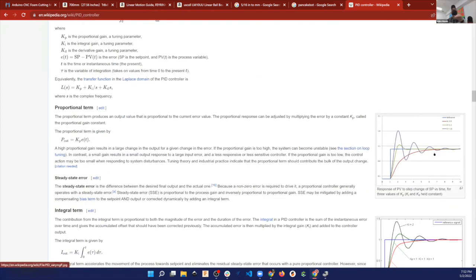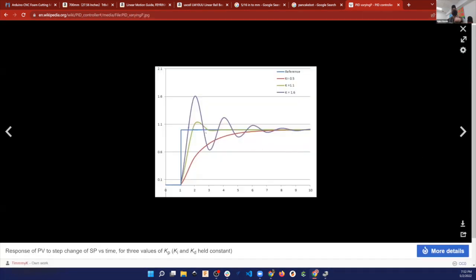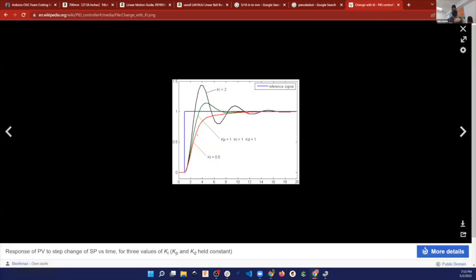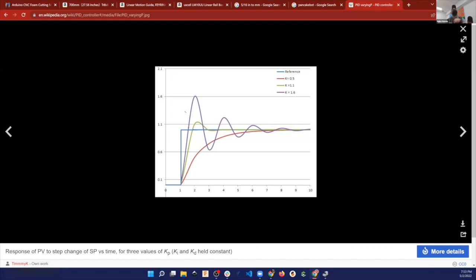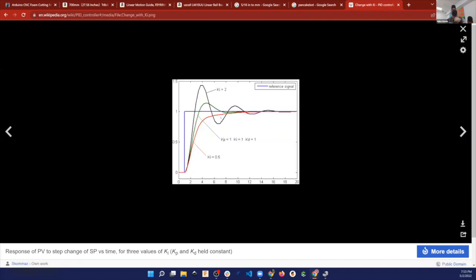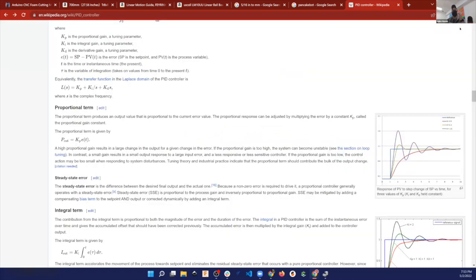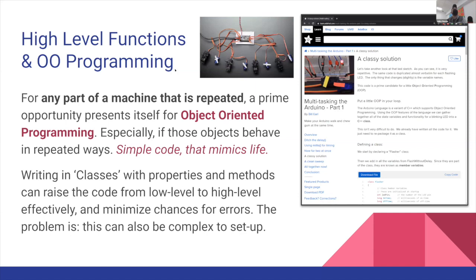It looks really aggressive, but here's basically the system that you could do, where you can tune in some of the different settings and you can make it so that your values give you different results. So here's like, I have the heated bed at 0, and now I want it to be up to 1. I want it to be warm. You can make that happen, and a PID controller will sort of zero it in. Some people really like this curve for a heated bed, so that it warms up, and then it sort of tapers its way onto the final temperature that you want. Those are really cool, really, really nerdy ways to better understand what's happening here. But those are high level pieces.